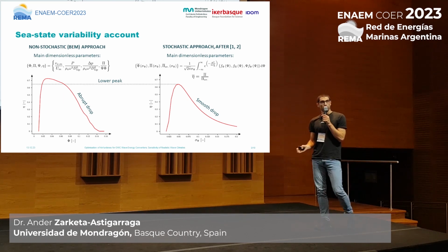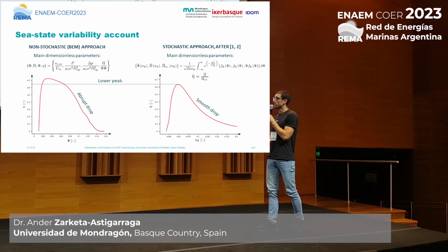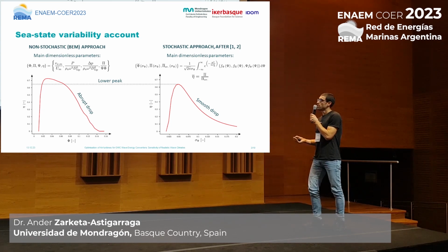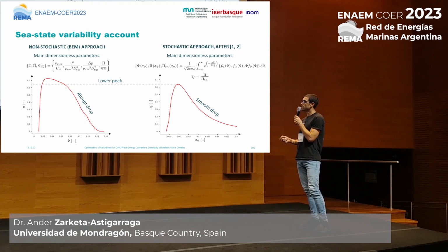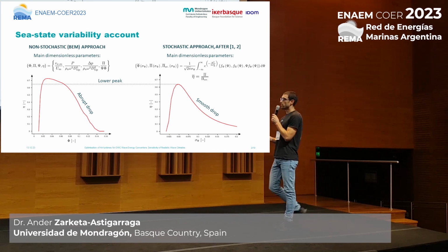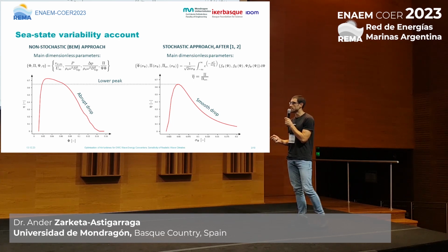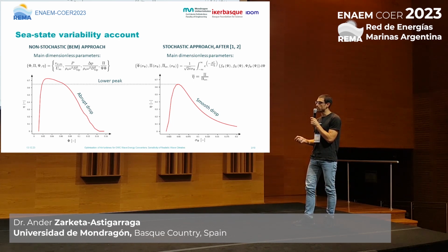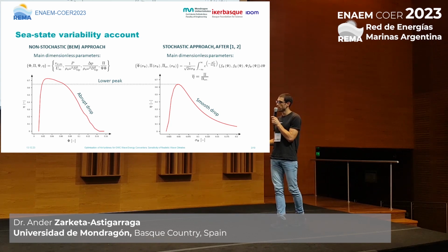Now, for reasons that I will explain shortly, we will be mainly interested in the evolution of the efficiency curve. At the bottom of the slide, you have both the static and the stochastic efficiency curves. The differences I want to point out on these two graphs are, first of all, that we are not plotting the same thing on the x-axis. We have the dimensionless flow coefficient here, whereas we have the dimensionless standard deviation of the pressure coefficient here.